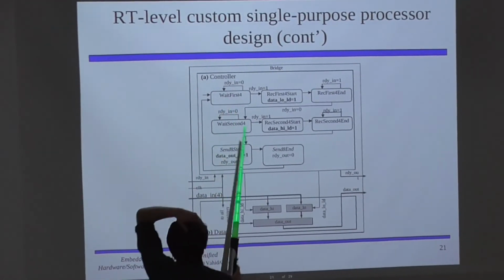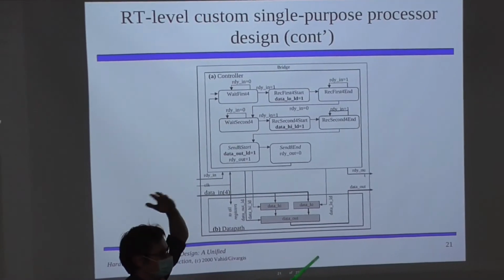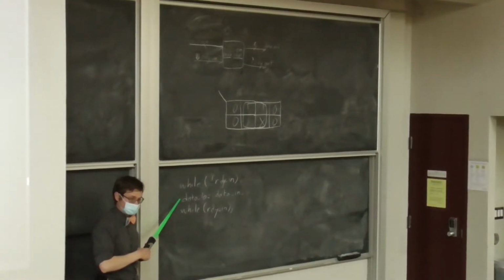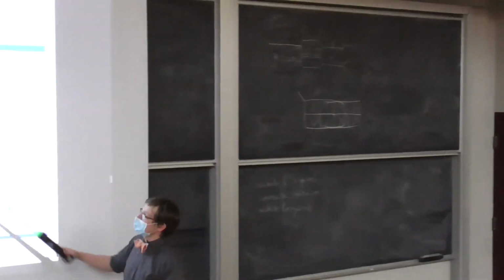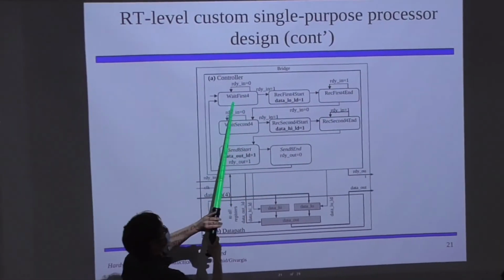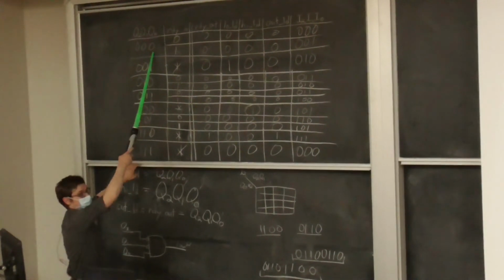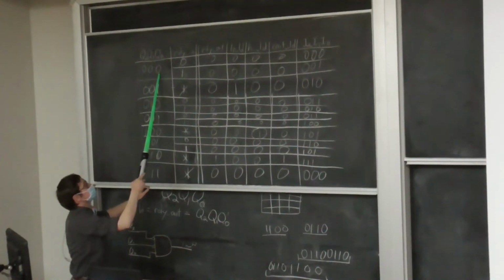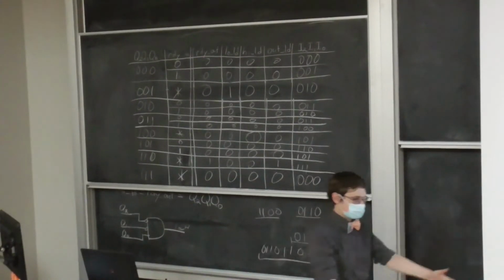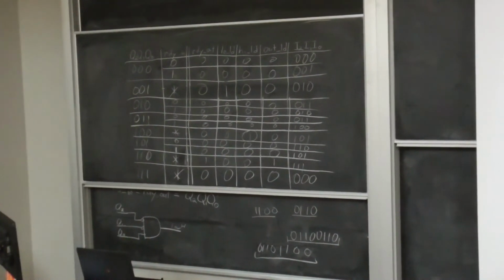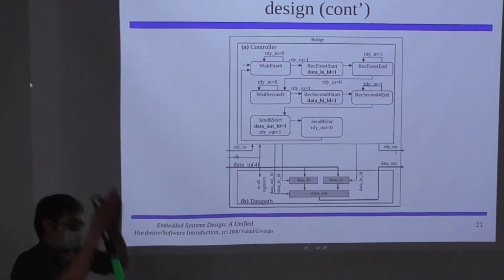Right? So essentially, it's this while loop, right? It's waiting until you hit the next one, or waiting until the signal flips and then you hit the next one. So in this case, in the state table, we just write down the state we're currently in. Ready in can be either 1 or 0, right? Because it's an input. We want to account for both cases, right? And in this case, it actually has a pretty extreme effect on the state itself.